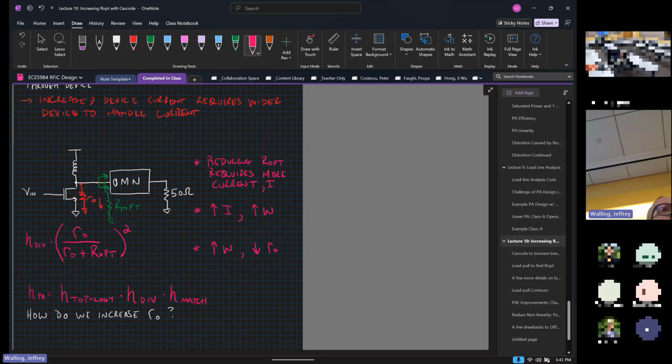So that output matching network also has some loss depending upon the size of the transform that it has to do. And remember, the bigger the transform we're making, the more loss that we're going to see in the matching network. And I'm not adding it here as necessarily part of the transmitting system, but technically we also do have to worry about the efficiency of the antenna. So this is how efficiently the antenna couples signal to the air. And if I look at this, I shouldn't say the efficiency of the PA. This is really the efficiency of the whole transmitter. Well, I'm not including other things. I'll say the PA for the time being. I'm not including things like the driver here. So I'll just say the PA.